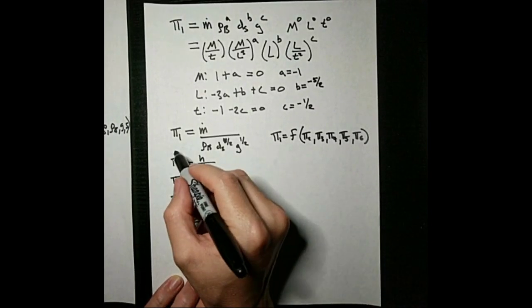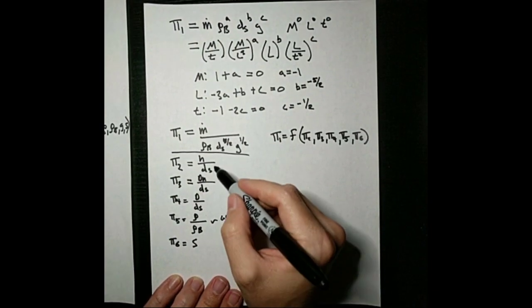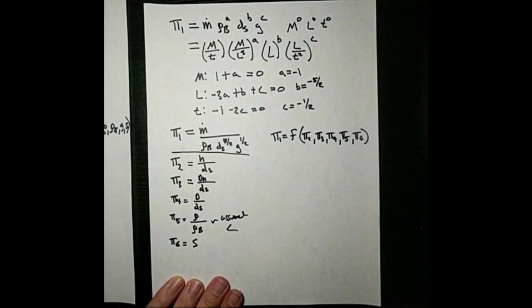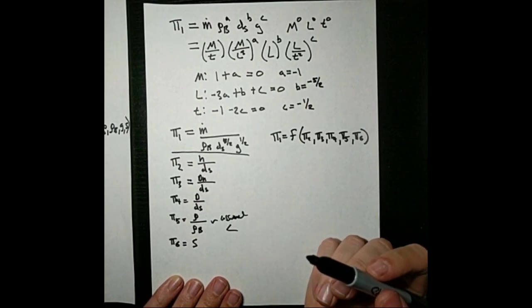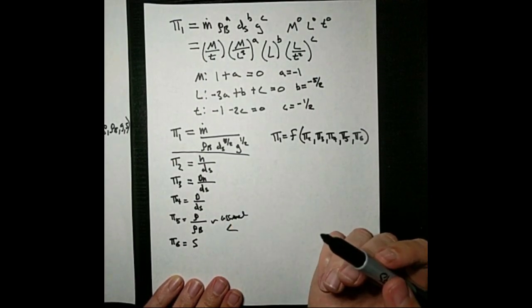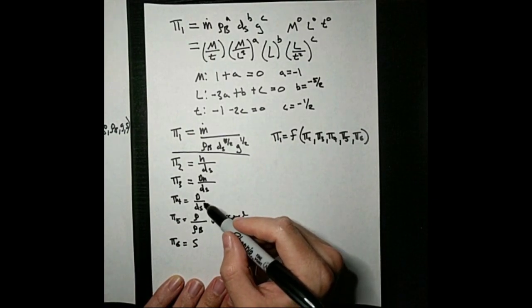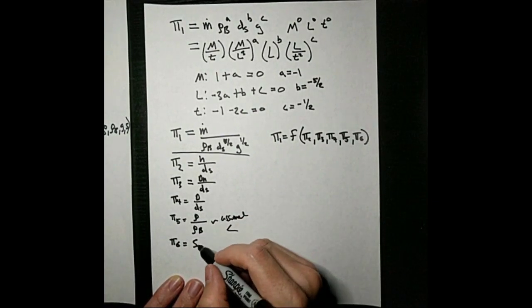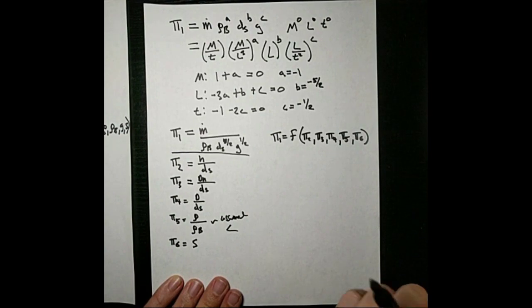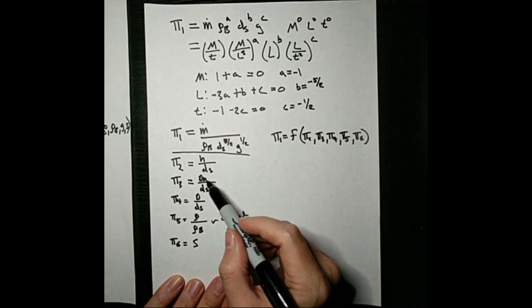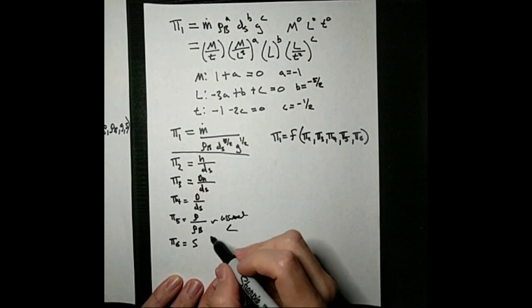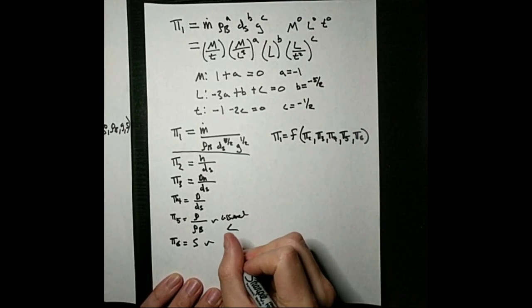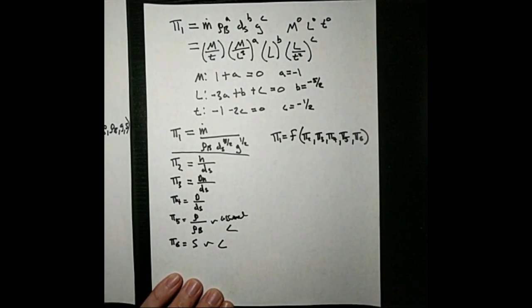So then of our other four parameters here that we're looking at, we've got dimensionless packing height, dimensionless hydraulic diameter of the orifice, so how large of an orifice are we flowing out of, dimensionless diameter of the column, and dimensionless shape. The hydraulic diameter of the orifice already accounts somewhat for the shape. So we will use just one shape. So we can say that that's a constant.